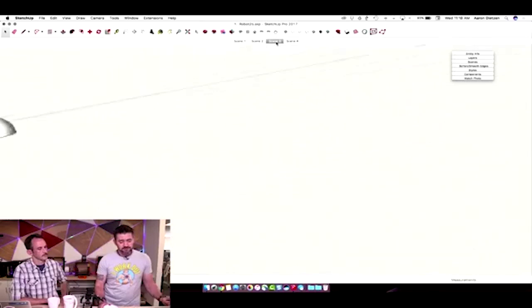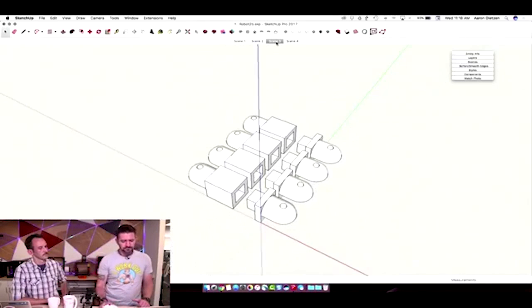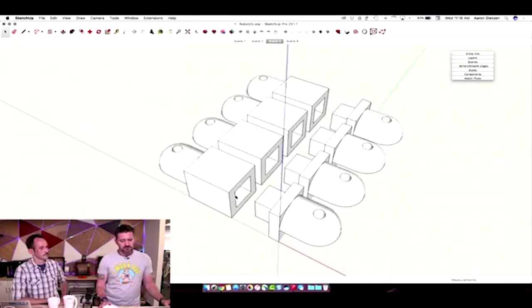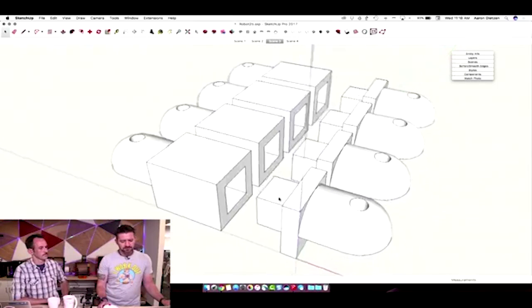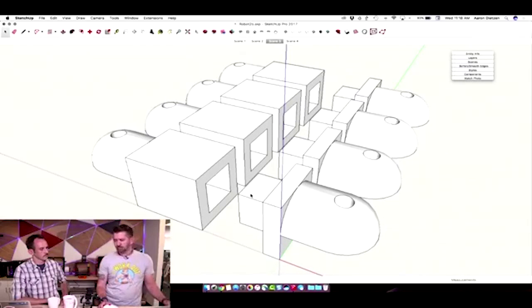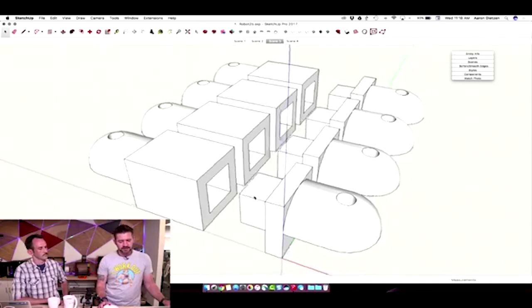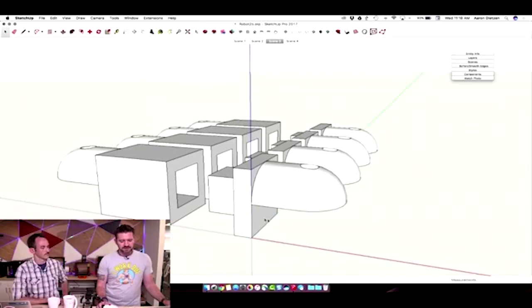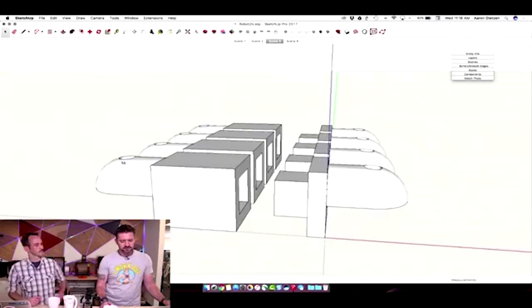So what I ended up doing was making a kind of a revision. So I actually broke what was one piece into 2 separate pieces. So I hollowed out this piece, put a little plug that would fit into this hole, again, 0.15 millimeter clearance around the whole thing, and this way I would get support material underneath both of these dome shapes.